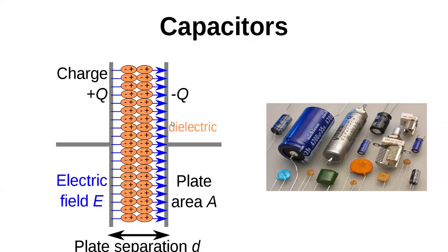And over on the left is just a symbol of a capacitor, showing the charge on the two plates and the dielectric in the middle, and how the charge on the dielectric is distributed. I think in reality, these atoms in the dielectric actually become dipoles, where the charge on the plates will attract the electrons over to one side of the atom. So instead of them running around in this little sphere, they tend to go more to one side, so it becomes kind of an oblong or elliptical shape. So one end of it tends to be negative and the other tends to be positive. That's not on the test, by the way.